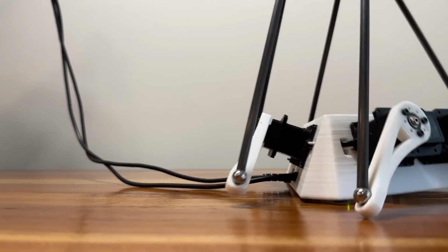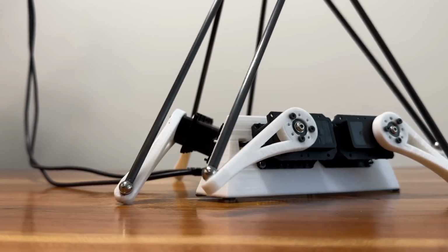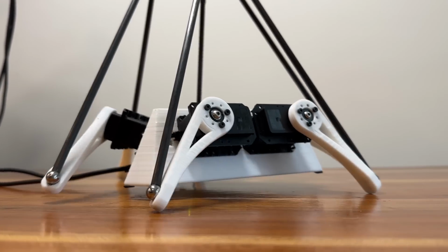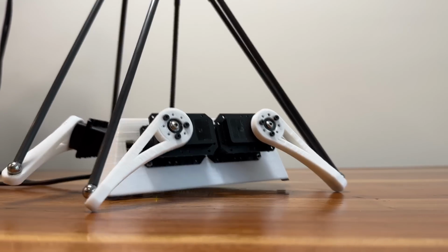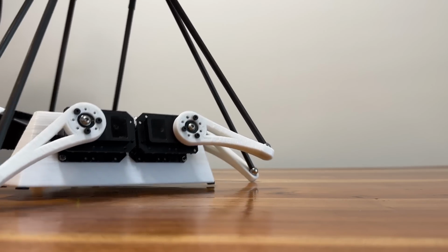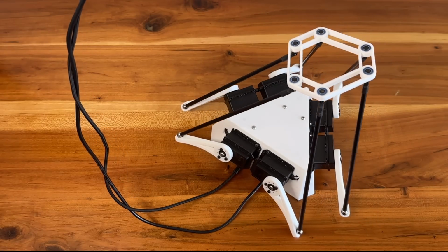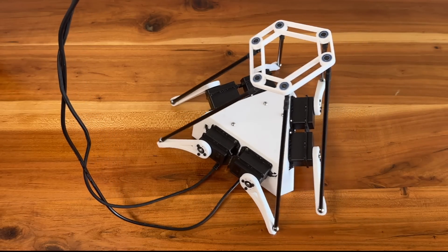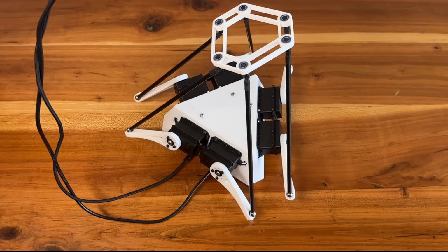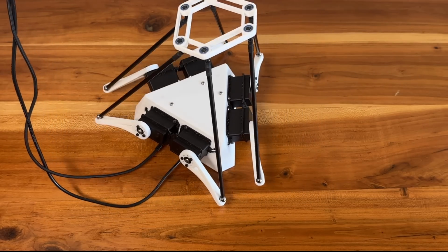I think the biggest limit on the robot's walking is the size of its base. There's only a small angle between where the arms hit the ground and their max travel. Additionally, all the dimensions of the arms, top plate, and base were never optimized for walking. I think it would be interesting to represent some of these dimensions in the genotypes and try to evolve the shape of the robot alongside its walking movement. It would be cool to see what a robot that evolved its shape and dimensions alongside its pattern of movement would look like.